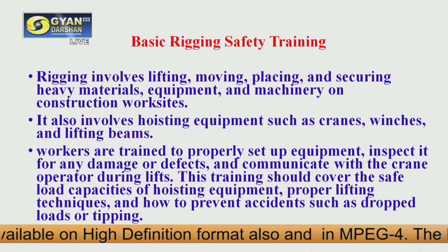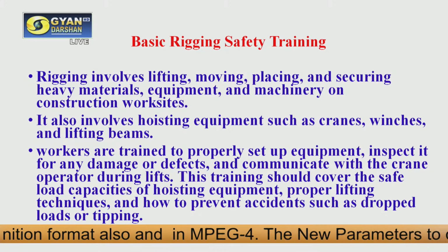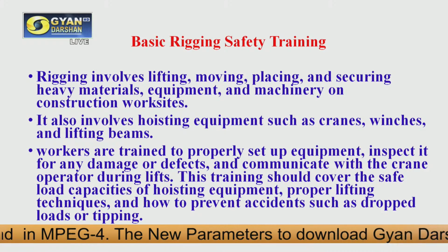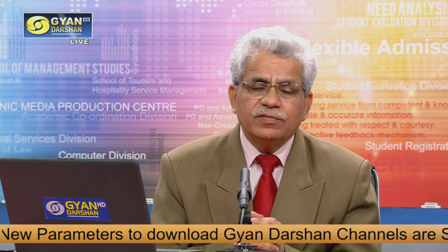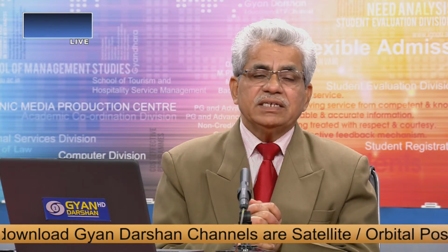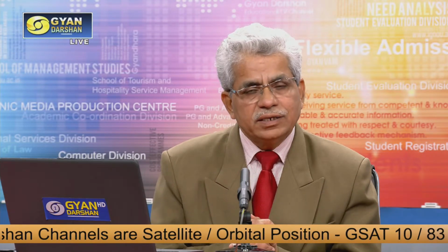So as you know, when we are lifting some load, moving or placing it, it depends on the posture of the worker how the worker will be safe or get an injury. Because if a worker is lifting a heavy load with a wrong posture, then there may be many problems to his back, his legs, his head, even shoulders. So they should be told what the proper way is to lift any load, especially manually.